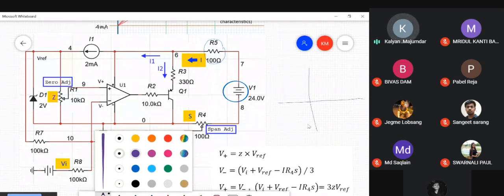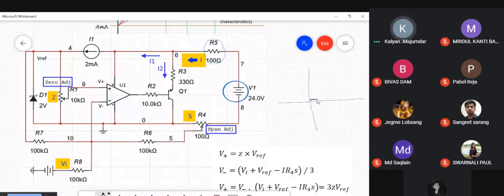If you plot the characteristics of a Zener diode, when it's forward biased, it acts like a simple diode. So exponential growth, this is voltage and this is current. When it is reverse biased, you have some breakdown voltage. Say this is the breakdown voltage. Until you reach that particular voltage, the current flowing through this reverse biased diode is very small. It's just a leakage current in the range of nano.